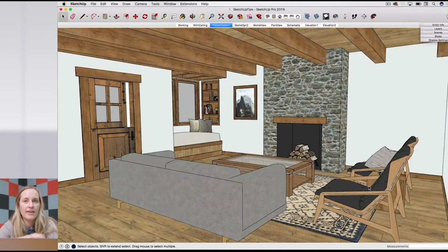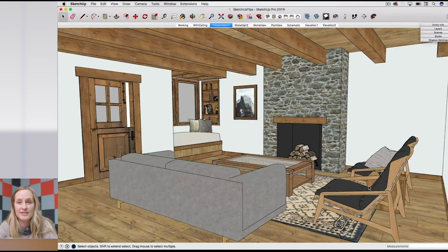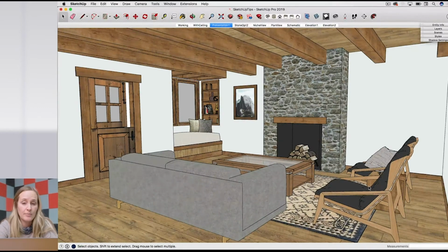You'll want to go ahead and develop that 3D model and then push off adding those materials and textures until you're ready. It's a couple of reasons. Number one, like I just said, it's part of the interior design process. We don't want to get too hung up on specific materials and colors. And then the second reason is that it can be more difficult to see what is going on with the edges and where those edges are when materials, especially like dark flooring materials, things like that, are added.